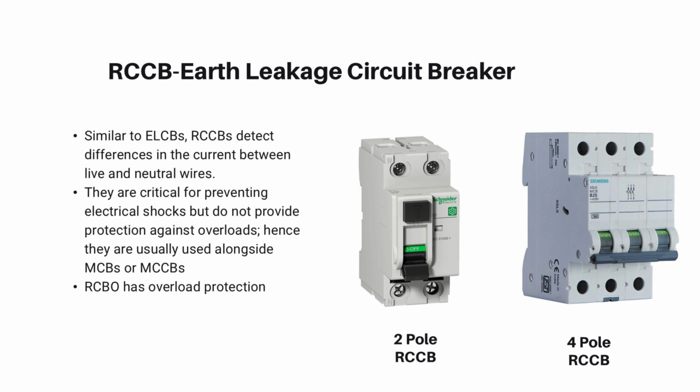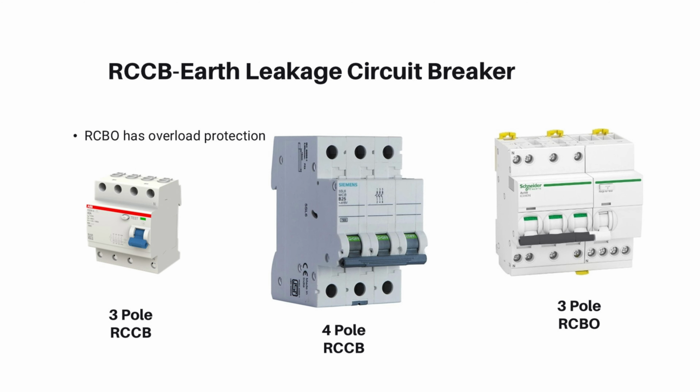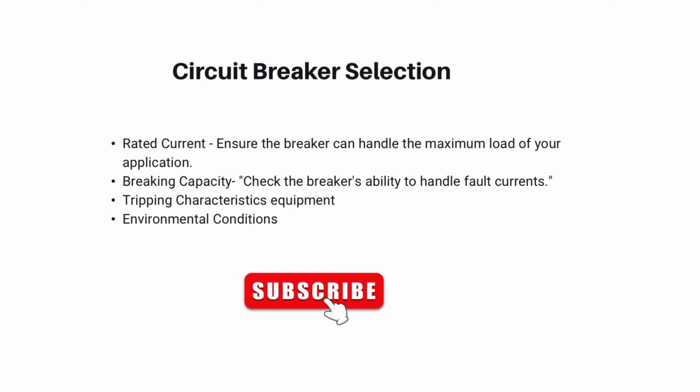The last type that we're going to look at today is the residual current circuit breaker, RCCB. This one is similar to an earth leakage circuit breaker. RCCBs detect differences in the current between live and neutral wires. They are critical for preventing electrical shocks, but they do not provide protection against overloads. Hence, they are usually used alongside MCBs or MCCBs.